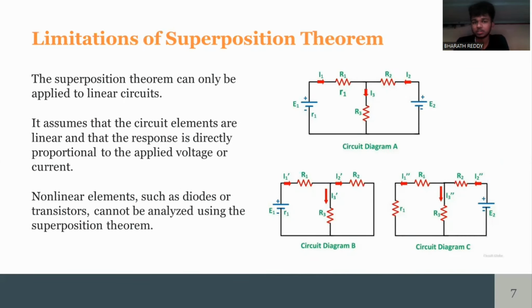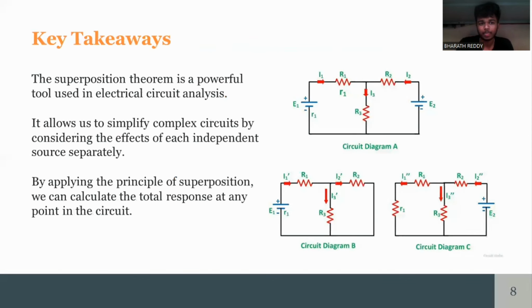Limitations of superposition theorem. The superposition theorem can only be applied to linear circuits. It assumes that the circuit elements are linear and the response is directly proportional to the applied voltage or current. Non-linear elements such as diodes and transistors cannot be analyzed using the superposition theorem.